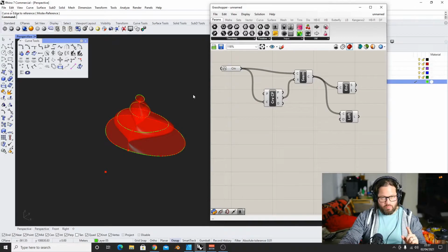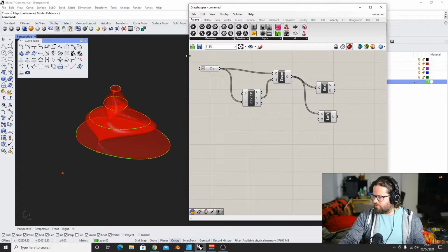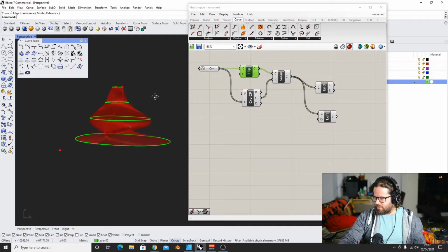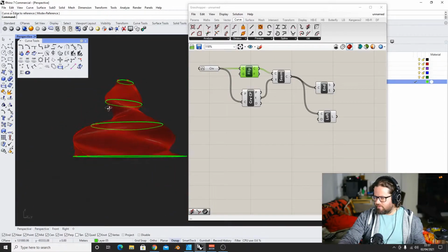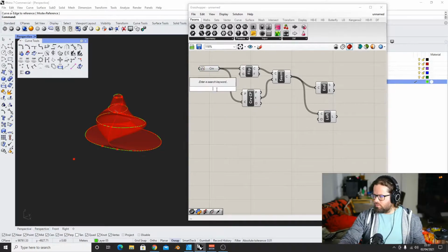And in Grasshopper, it works the same way. And by adding another tool here, to sort it out automatically, you can actually do this. And so flip curve, if you put this in here, it flipped all the curves, but now it's the same problem as before. But here you have an option to put a guide curve, so you can actually do select. You can select one curve separately, or you do list item.